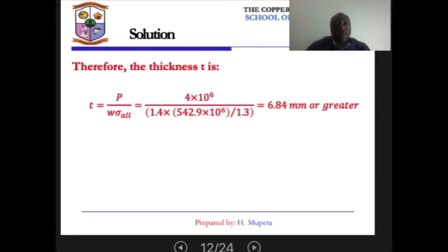So the yield strength of the material would limit the thickness of the geometry when you are dealing with the weaker alloy. Okay, and so from there we can conclude that the weaker alloy leads to a thinner and lighter weight choice, since the fracture mode differs between the weaker alloy and the stronger alloy.